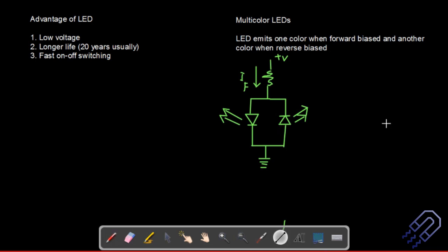The idea is simple here. What happens here is this. Okay, you have the electrons here and you have the holes here. And as soon as we have the electrons here, it gets de-excited. And as soon as it gets de-excited, we say that they are recombining. Okay, that means they are coming back to the holes. They are recombining, or they are occupying the positions which are vacant here. As soon as they come out, you are going to get an emission of radiation.